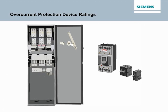Every circuit breaker or fusible switch also has a continuous current rating. For a circuit breaker, that's the maximum continuous current a circuit breaker is designed to carry without tripping. For a fusible switch, it's the maximum continuous current that the fuse is designed to carry without opening. The current rating is sometimes referred to as the ampere rating because the unit of measure is amperes, or amps.